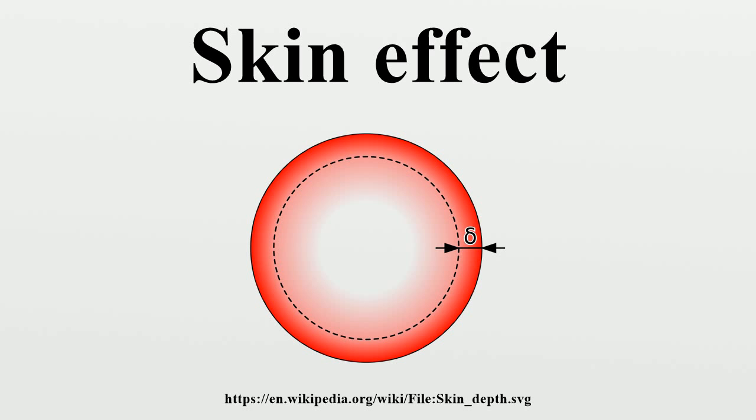The first inductance is associated with the magnetic field in the region with radius less than A, the region inside the center conductor. The second inductance is associated with the magnetic field in the region between the 2 conductors. The third inductance is associated with the magnetic field inside the shield conductor. The net electrical inductance is due to all 3 contributions, and is given by the frequently cited formula for inductance L per length D of a coaxial cable.